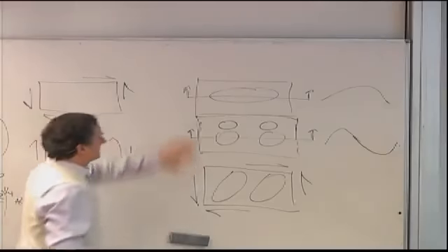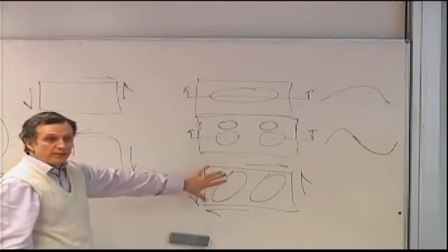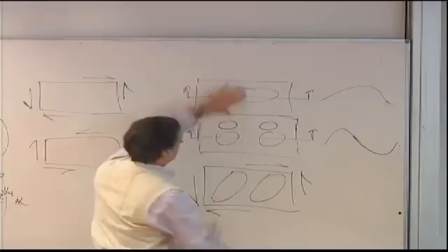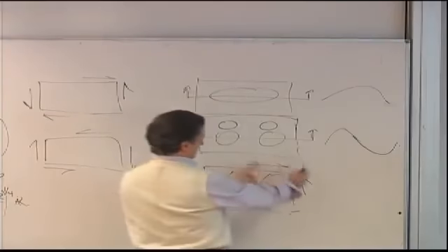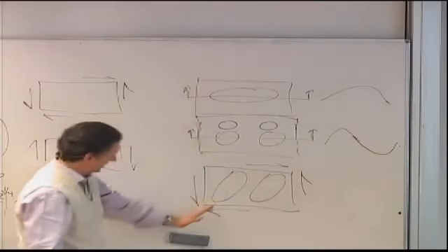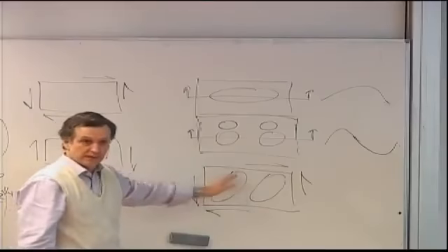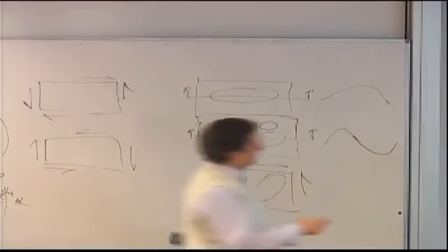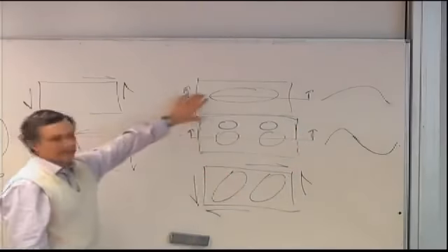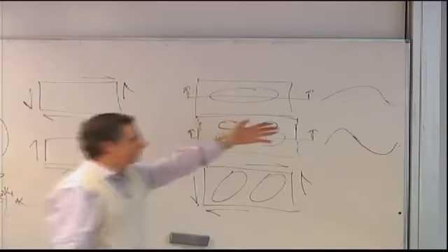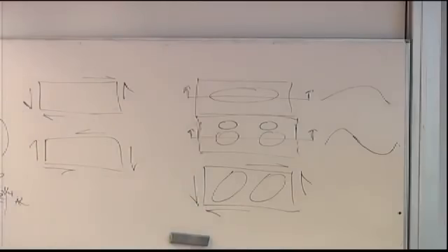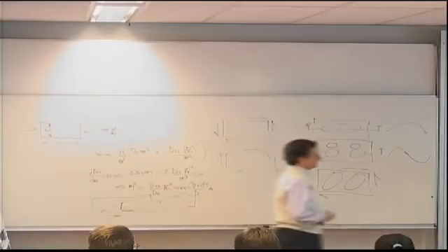So if I have shear buckling of a plate, this half wave that's perfectly nicely symmetrically located is actually rotated, and the direction of the loading tells us whether it's rotated this way or that way. And in fact, it takes a lot of algebra, but you can calculate the angle of inclination of this. Individual terms alone have no chance of reproducing this rotation because they're perfectly symmetric. So physically, if I only use a single term, the problem is too far from what I'm trying to approximate. And that's the physical reason behind why it's not going to work with a single term.